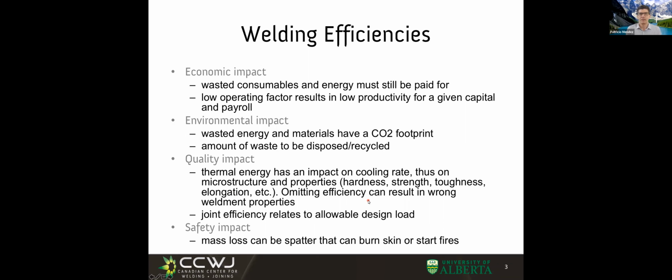Quality impact, for example, when we already discussed how heat input affects cooling rate, and how if we have a big heat input, we might have a slow cooling rate. That we discussed. Now, what we just glanced on is that if we talk about the nominal heat input, that might be a larger value than the actual heat input, and the corresponding cooling rates might be also affected. Sometimes it doesn't matter, sometimes it matters. We'll have all that well understood.